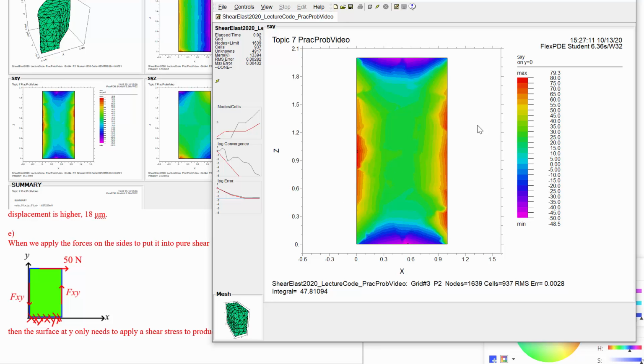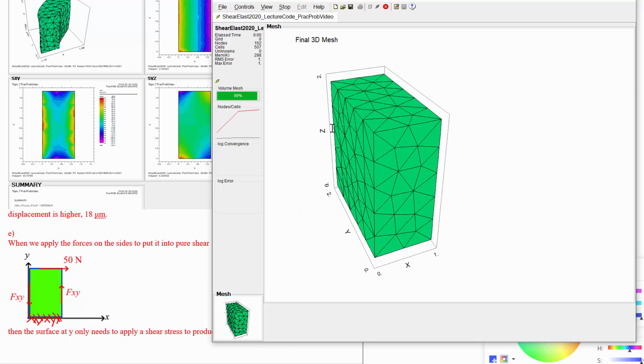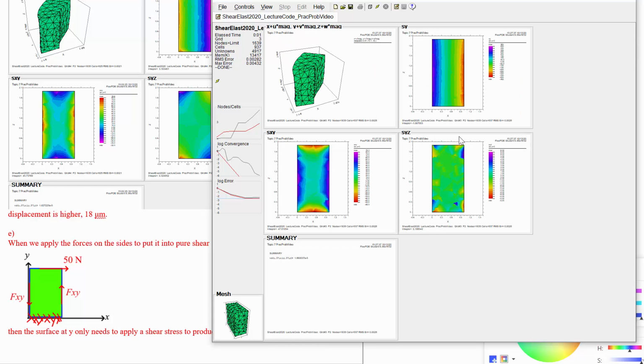So spectral colors, why is it called spectral colors? That's to do with the light spectrum. So in optics, purple is like the highest energy, right? Red is the lowest energy. But you tend to think of a heat map kind of the opposite. Like if you see blue on a weather map, and then you see other places where it's red, you're like, oh, the red is hotter. But in terms of light energy, blue is higher energy than red. So from a spectrum perspective, purple is where the highest numbers are, and red is the lowest. Yeah. So the color doesn't mean much if you don't also look at the color bar.